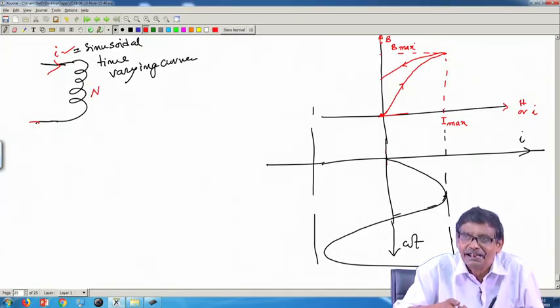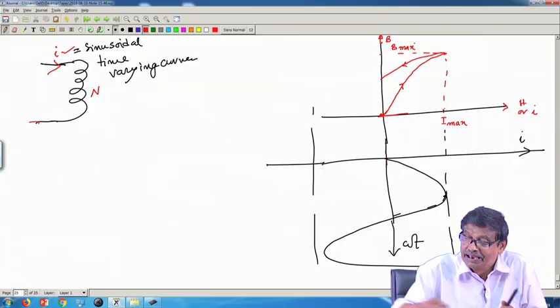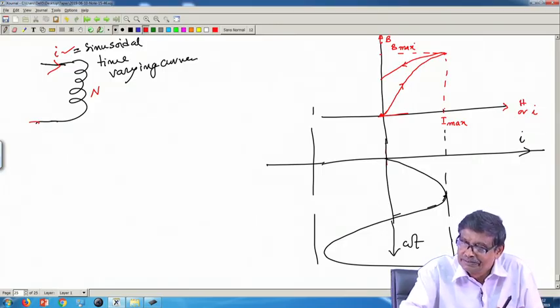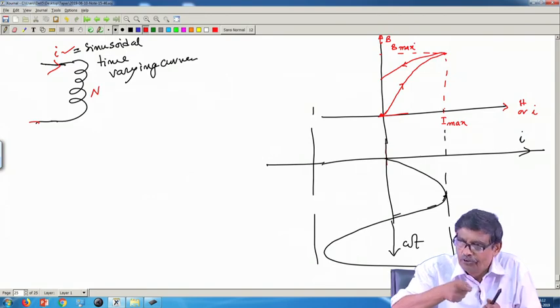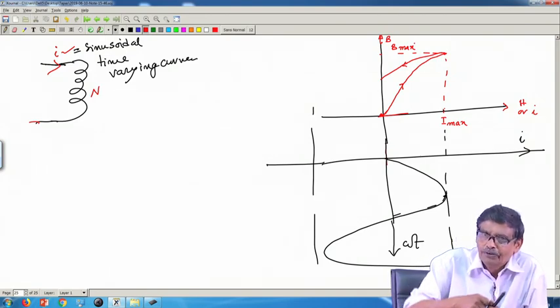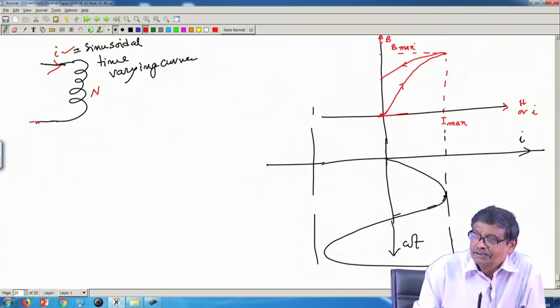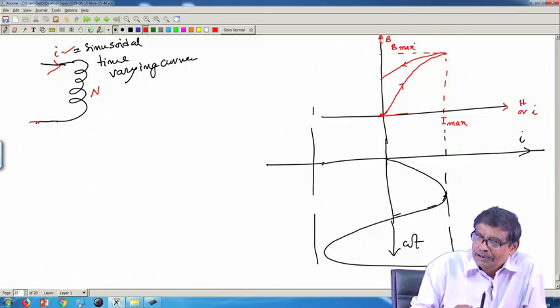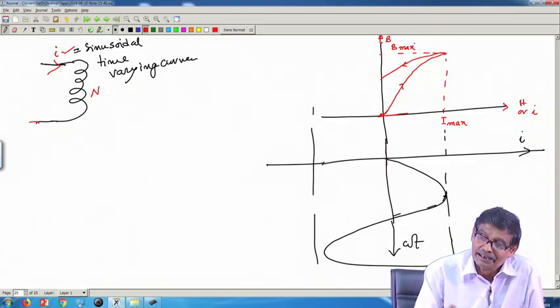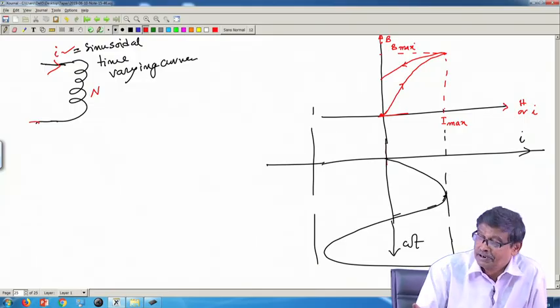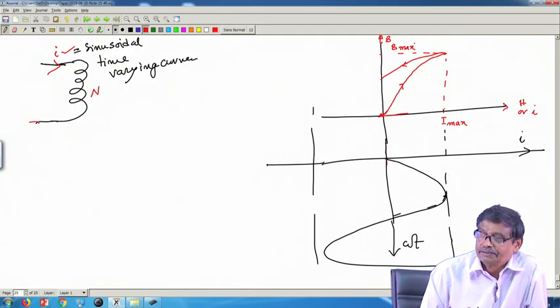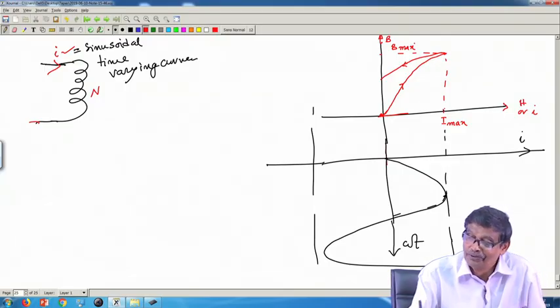After they have reached that, you are applying a negative H, then they will follow that instruction, they will try to follow, but in a sluggish manner, and this is called hysteresis. It will lag behind. Okay. The way they went up while you are decreasing H, it will be sluggish, sort of inertia or whatever you call it. It will go like this.